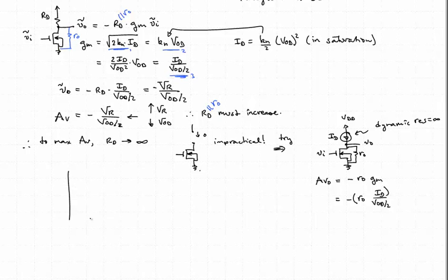Let me draw a transistor output curve for a MOSFET. We have this family of curves, and ideally in the saturation region, which is right here, the current is independent of VDS. But the reality is that there is a finite slope, a non-zero slope.